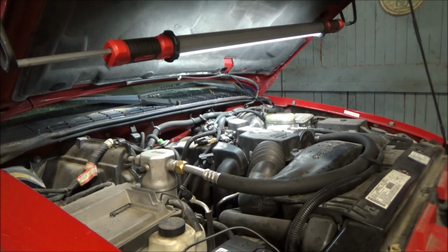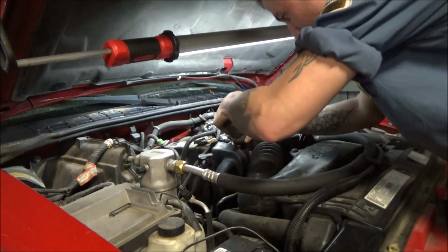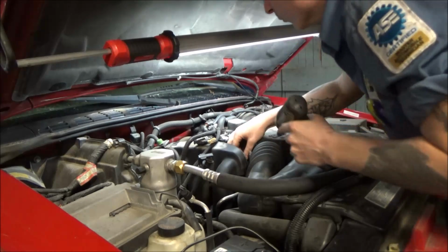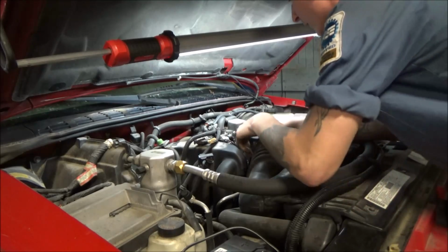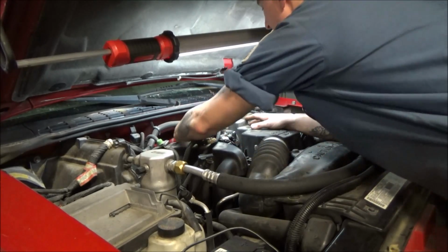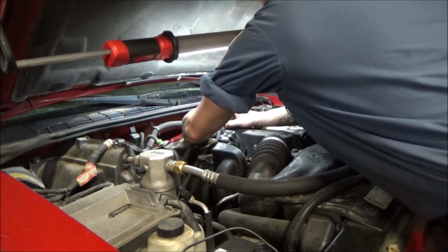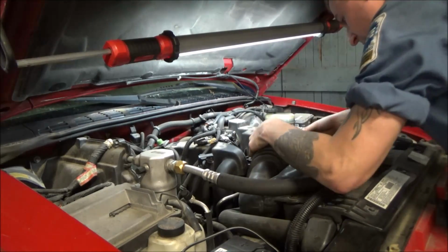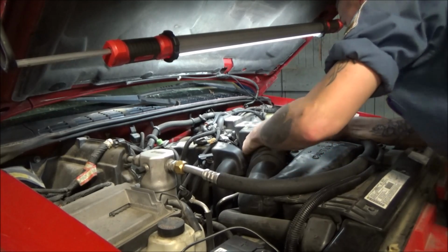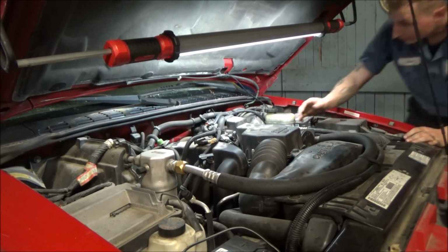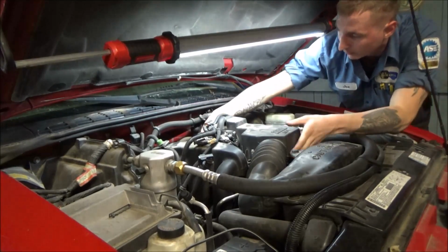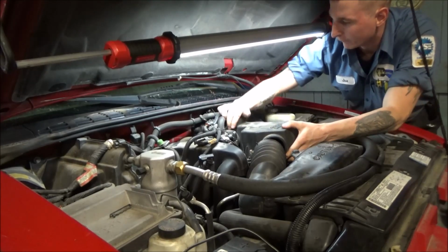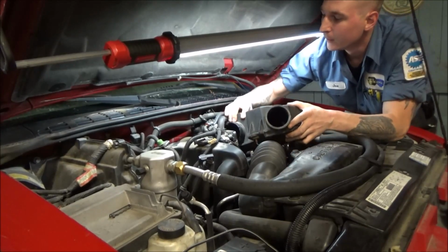But one thing I'll talk about, guys, while I do this is the sweep test that we originally executed, where we slowly open that throttle plate up. That's an excellent test at catching glitches in a throttle position sensor signal. And oftentimes, guys, when you see those glitches, it's very likely going to be the throttle position sensor. There's a very small potential that it could be something like a wiring problem, guys, but honestly, it's pretty doubtful.